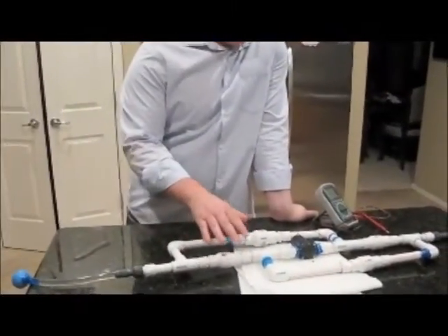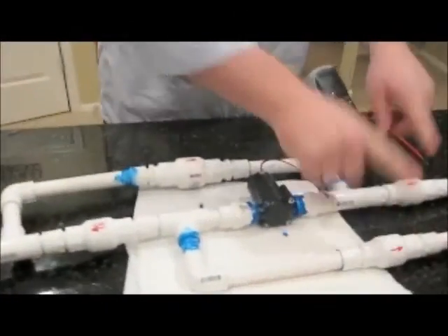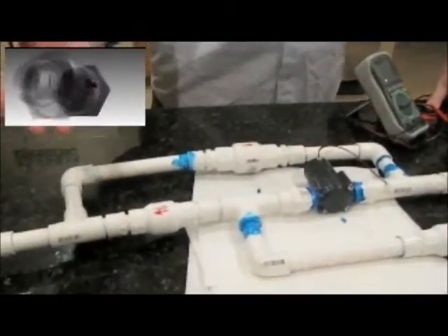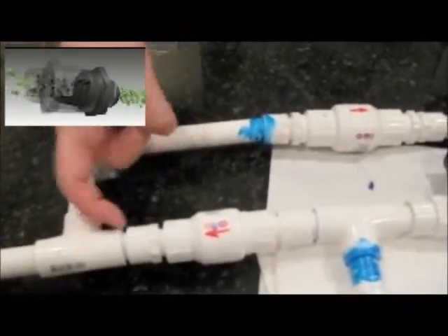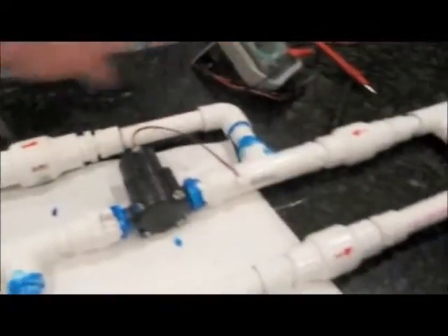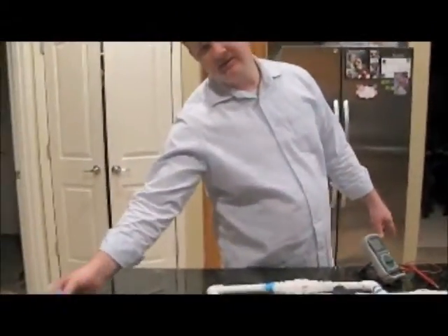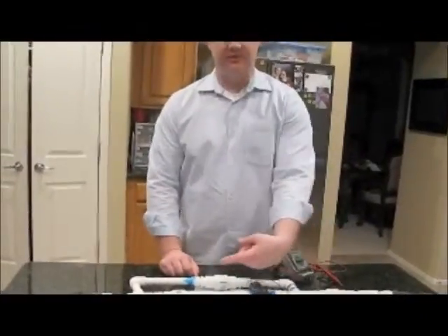So here, though, are some of the main components of this fluid system. Here you have 4 individual check valves. You can see that these are one-way directional valves for those that don't know what a check valve is. So in other words, water can flow this way through this valve, but it cannot flow backwards. And there's a system of these throughout the design. What these do is direct the water to go one direction through the hydroelectric generator at all times. So regardless of whether you press on this reservoir of fluid or on this reservoir of fluid over on this end, water will always flow this way through the generator.